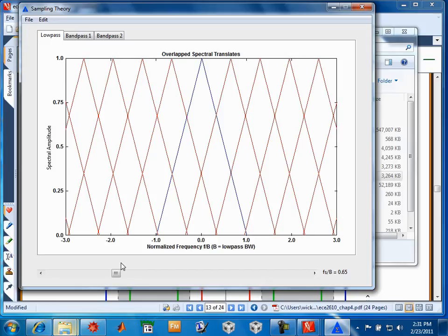It doesn't have to just be the signal content. Suppose you had a really wideband sampler, a really wideband front end of your system, and you didn't protect it, and there was a bunch of noise out there. The noise will alias down and stack up into the band of interest too, so noise will just pile up and it will sound just plain noisy due to ignorance about aliasing. It's intriguing, I guess, is what I'd say.